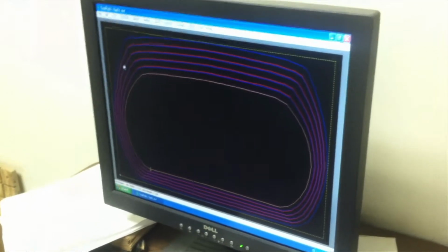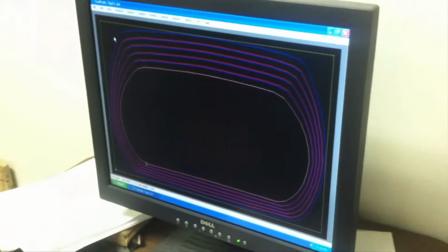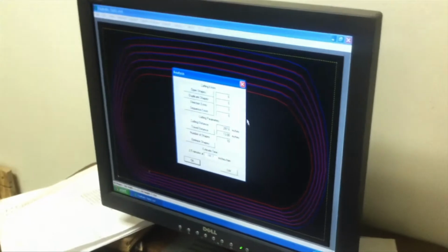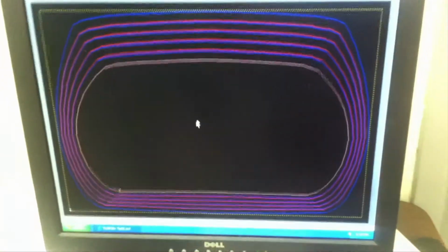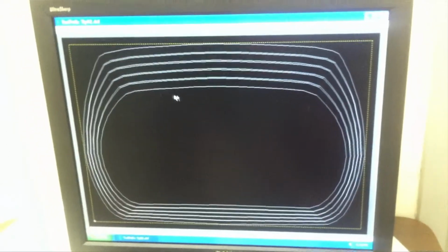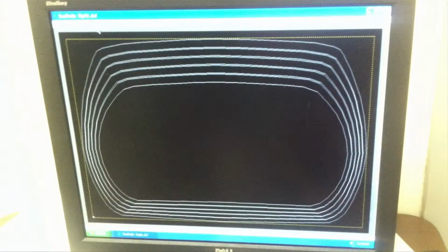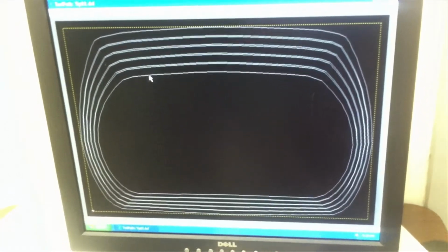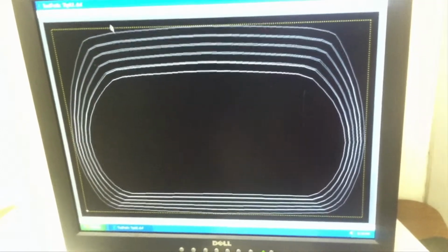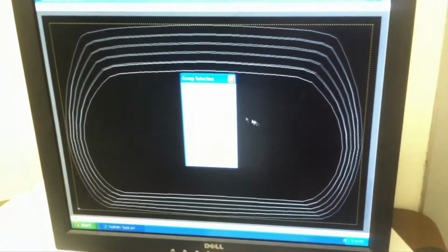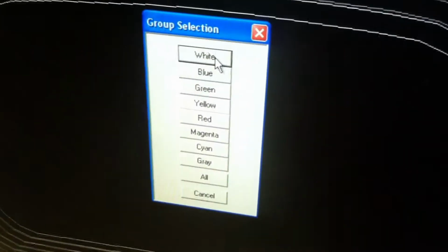Alright. First step is to go to analysis and make sure these are all 0. Only standard right here. After that, you want to go to groups. This is where we're going to group everything. First you go move to group. We're going to click the innermost and then the next innermost, so there's going to be 2 things selected. Say to group. This group will be white.